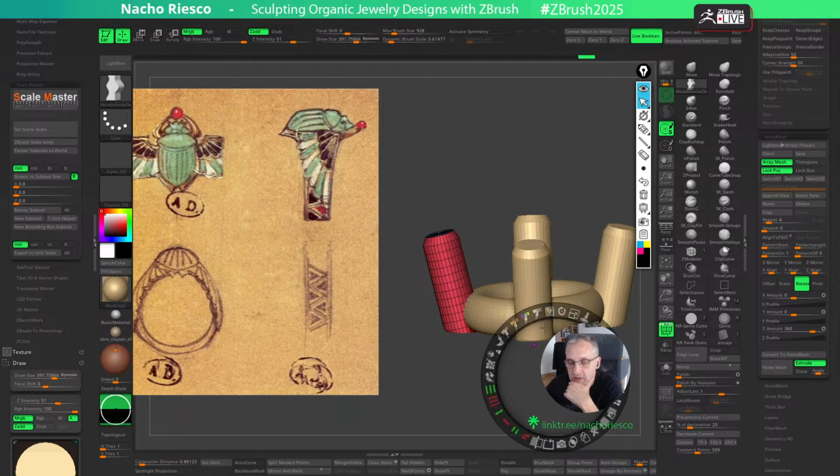No, the topology is not a mess because, when you are creating a boolean from objects with different topologies, the result is composed of different portions of different meshes. But depending on what you are looking for, you can use ZRemesher based on different polygroups, and you can retopologize it manually.